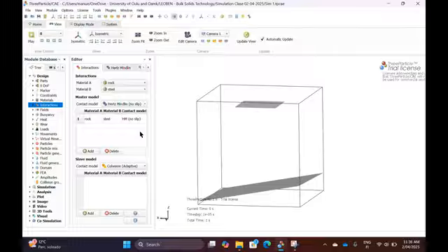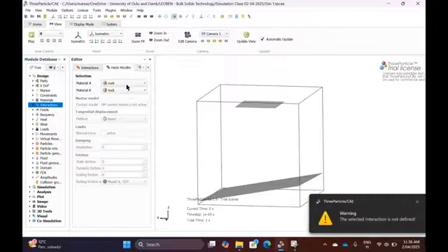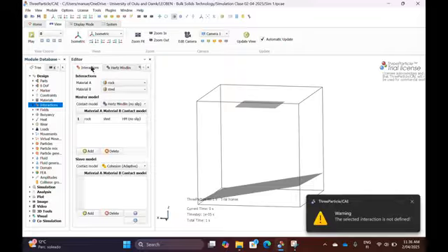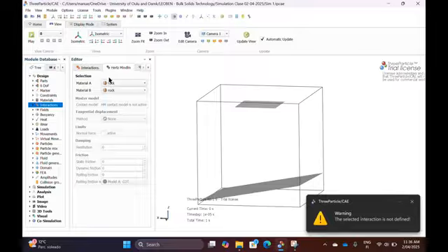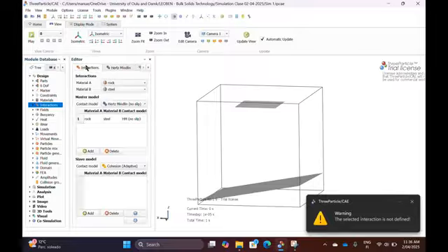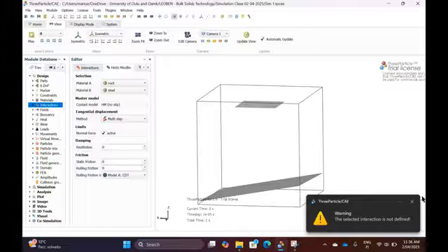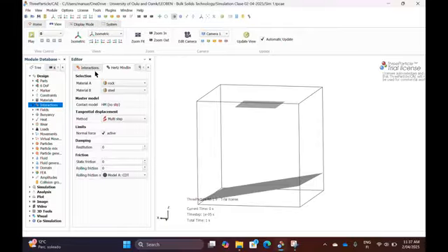We double click it, and we have some details to fill in. We have A, B, C. A lot of stuff to go into, but as you remember, what this might be, restitution. Particle falling from a certain height, jumping back. Let's give that 0.2, for example. A little bit of damping, not too much, not too little. Let's start with something between 0 and 1. So it's the restitution, that the particle jumps back.